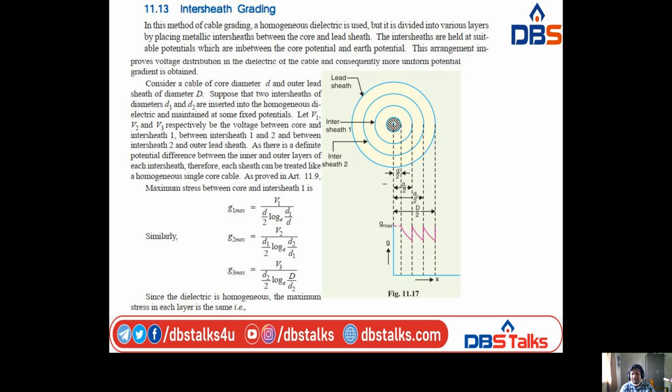So this arrangement may improve the voltage distribution in the dielectric of a cable, and consequently a more uniform potential gradient is obtained by this method only. That's why this is more important. Sometimes they ask a question like this: explain the inter-sheath grading briefly, or explain the grading of cables.